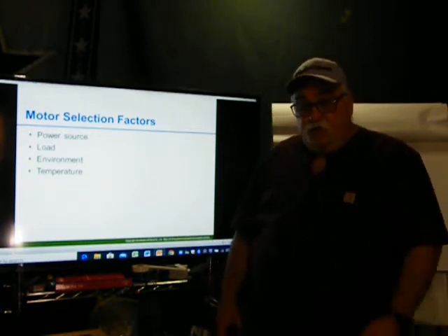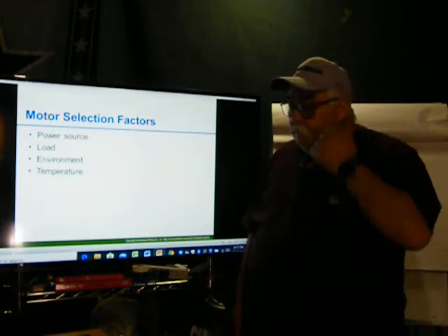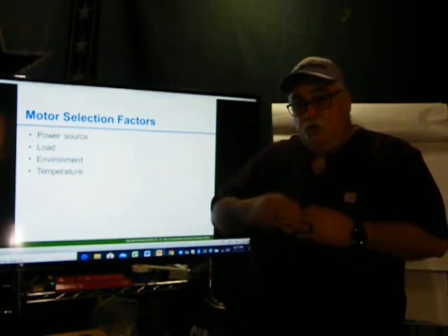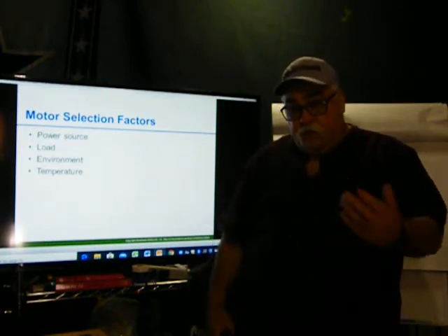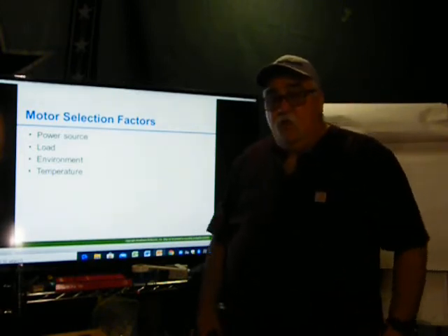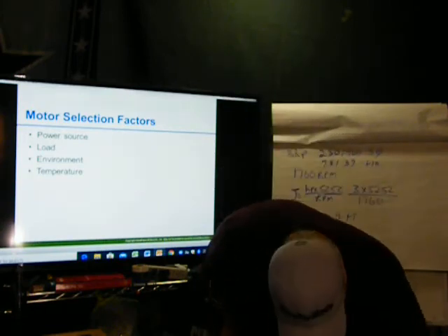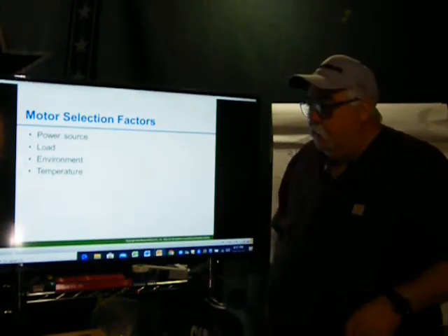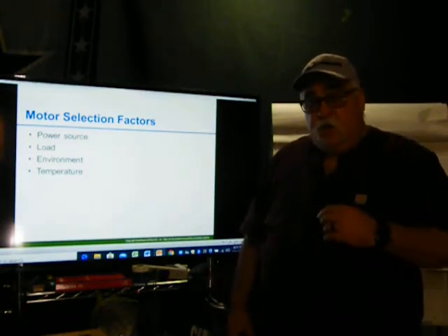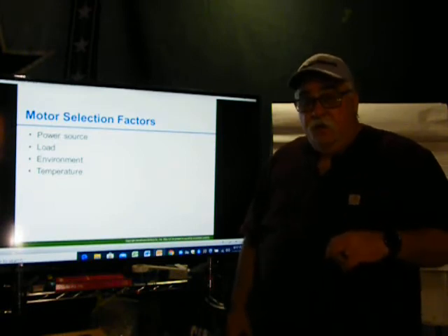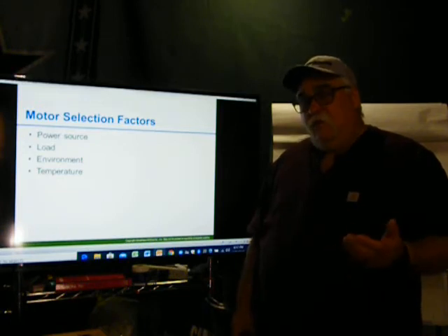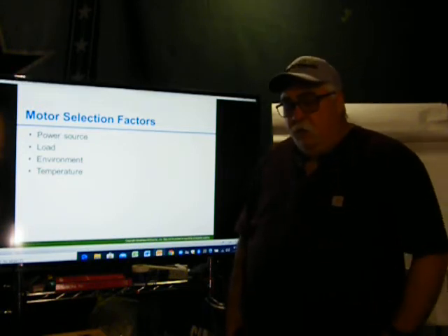So I called Germany and was able to get one of their engineers, and we talked about what we could do, because it was slicing too slow and making too many nicks, so the meat wasn't passing inspection. A lot of the meat being sliced ended up going back to get redone. He told us the best thing to do was to change that AC motor to a DC motor, so we could kick up the RPMs to 4,000 to 5,000 RPM, or he said we could double, maybe even a little bit more.